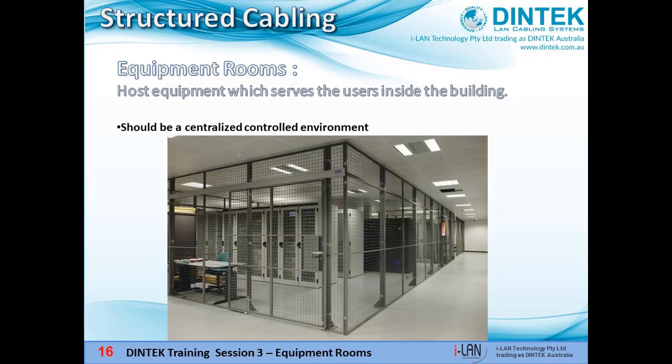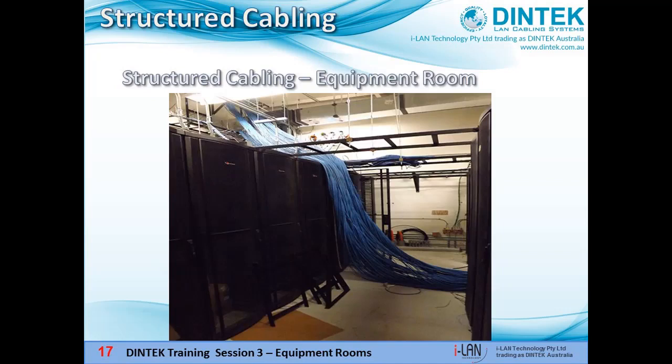Consideration also needs to be given to the overall size of the room, with appropriate allowances for future expansion, and overall temperature for equipment to operate at maximum efficiency. There are other regulations like being fitted with smoke detectors, emergency lighting, fireproof doors, CO2 fire extinguishers and rodent proofing. The requirements that cover design and other functional requirements for equipment rooms are provided by the Pathways and Spaces standards such as ANSI TIA 569-A.